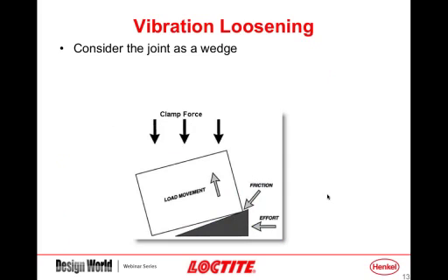So returning to how you get loosening, again, we started out the presentation by saying that if you unwound the thread from a fastener and you drive the two faces, the nut and the bolt, over each other, you end up with a stretching of the bolt, and you get a lot of friction, particularly on the thread roots. The clamp force is holding this together, and if you get any type of movement between the surfaces, you will actually lead to an unloading of these threads.